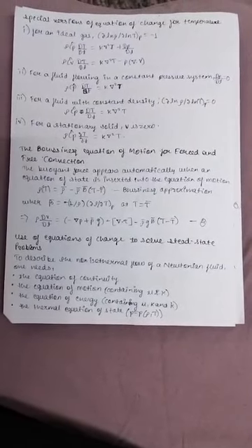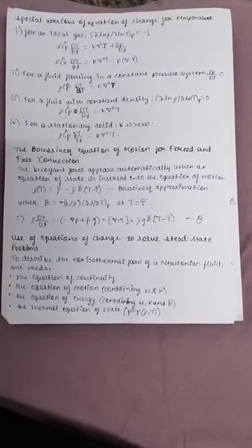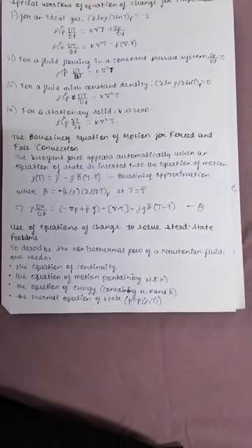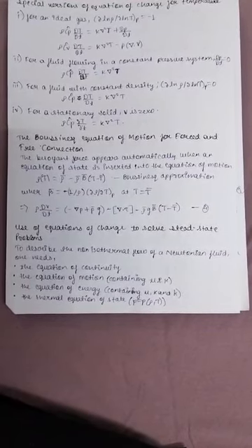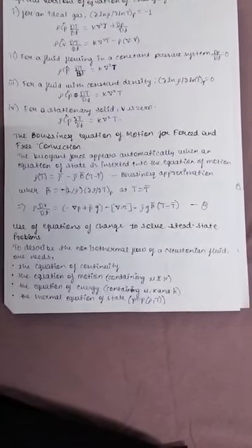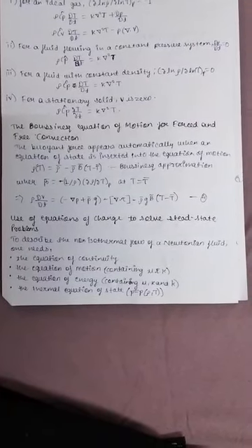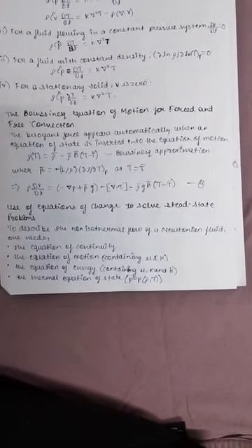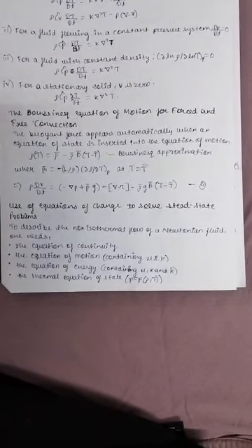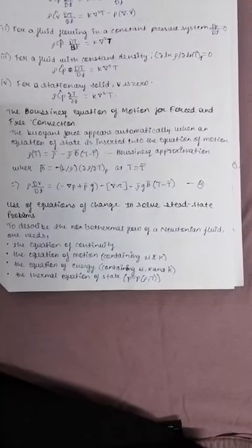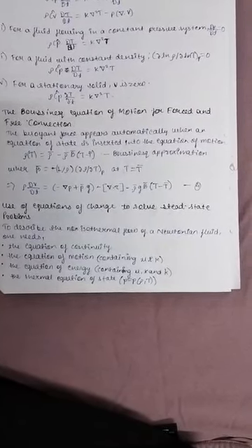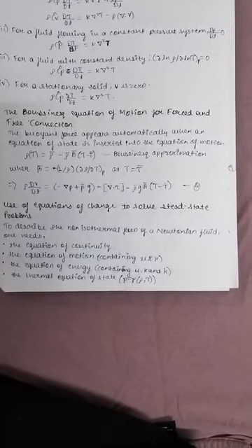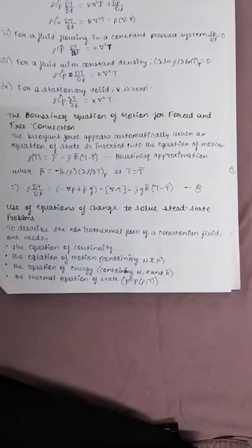Now let's look at the special versions of the equation of change for temperature. Case number 1, for an ideal gas, the quantity ∂ln ρ/∂ln T at constant pressure equals minus 1. So the temperature equation becomes ρĈp DT/Dt equals k∇²T plus Dp/Dt. And using Ĉv, it becomes ρĈv DT/Dt equals k∇²T minus p times ∇·v.